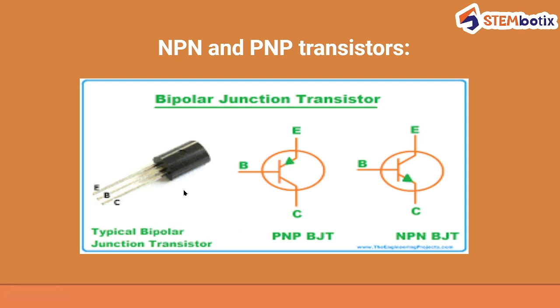Through this sensor, the power source turns on, and this will provide a specified amount of current to flow through the base. As soon as current flows through the base, it will turn on the light bulb. And that's how you can use a transistor to switch on an external or main circuit.